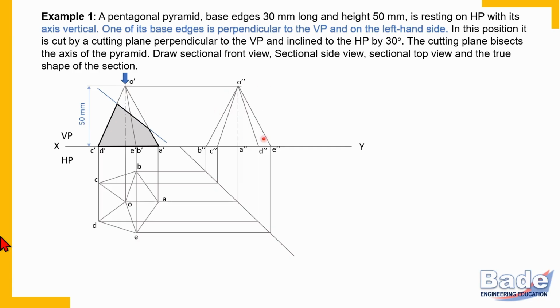Now it is left side view. Observer is watching from left, imagine. And now you will find that from left side this section is hidden. And that means this cutting line orientation is not correct. Now, suppose we draw cutting line in this manner.